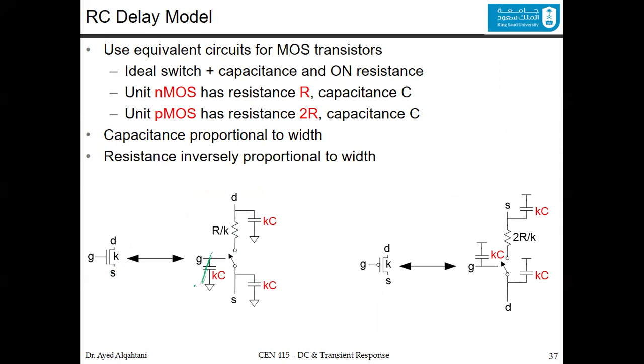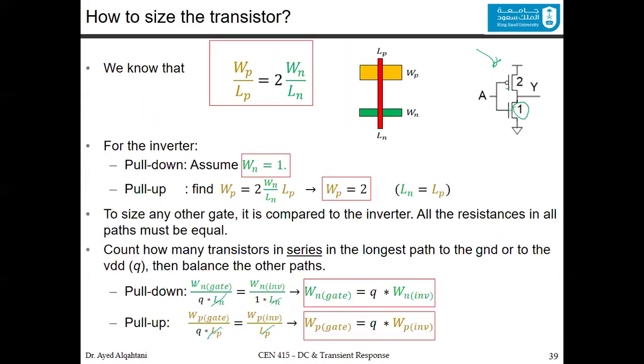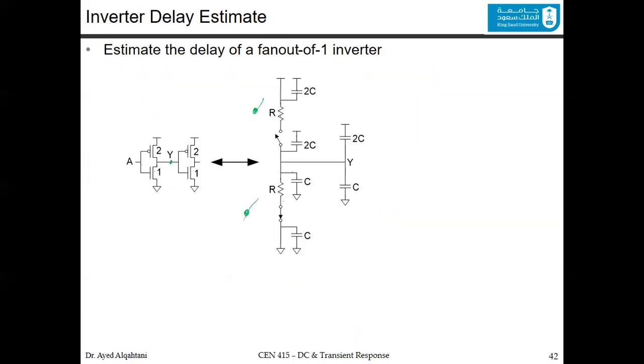Now this one I crossed in the example. Also, I could cross this one and this one. The reason is that it's actually VDD on one terminal and another VDD on the other terminal of the capacitor, which means that this one doesn't need time.